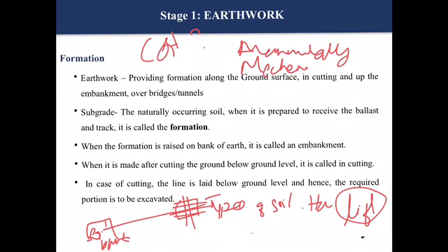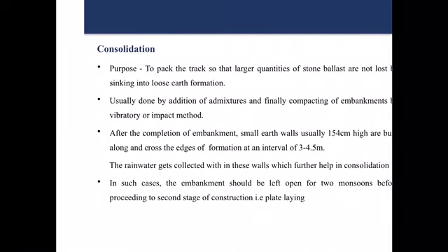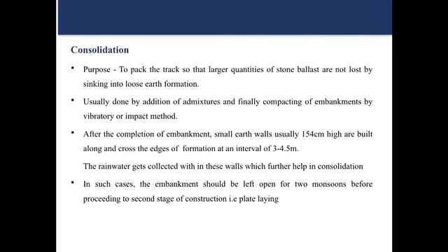And then after the earthwork is completed, the formation level is done and the formation is prepared. The next step is to go for the consolidation. So why is the consolidation required here? Once you prepare the formation, there are chances that the formation level which you have constructed may undergo volume changes because of the variation in the moisture content.